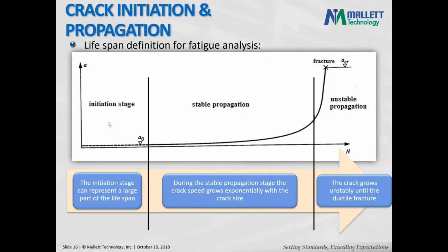So on this slide here, we kind of talk about the initiation stage. The initiation stage can represent a large part of the lifespan. And this crack initiation stage is usually, in our calculations, what we denote as the regular fatigue life. It could be stress cycle or strain cycle fatigue, but this crack initiation stage is where regular fatigue calculations end.